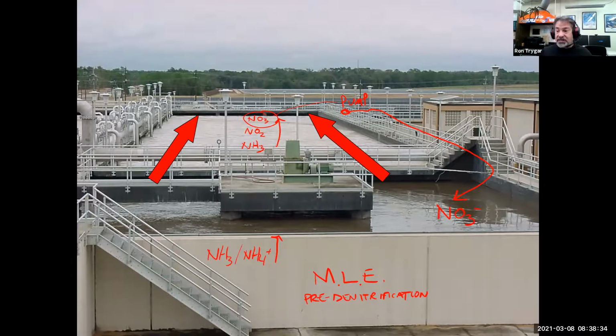It's going to stay relatively stable or constant through the basin, and it's going to migrate its way into the aeration tank. So the first basin in the process doesn't do a whole lot with respect to the ammonia or ammonium that's present. At least it shouldn't, because we're not actually aerating that basin and we're not supplying that 4.6 parts of oxygen needed for nitrification. So it's all about denitrification in that very first basin.